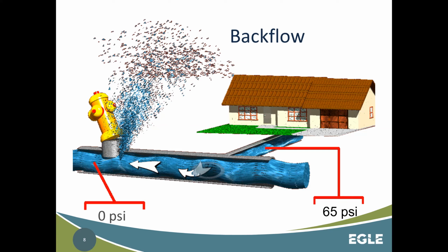But remember the example that I was talking about? If I had a Miracle-Gro can, let's say there's a Miracle-Gro can here on the garden hose, it might only affect my house, the service, or it might come out here and go into a couple service lines once this is fixed and recharged with pressure. So that's why cross connections are an issue.